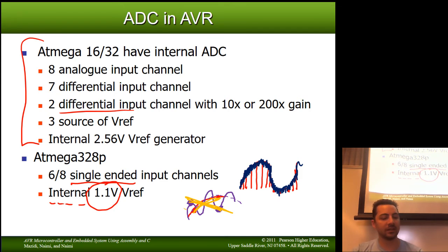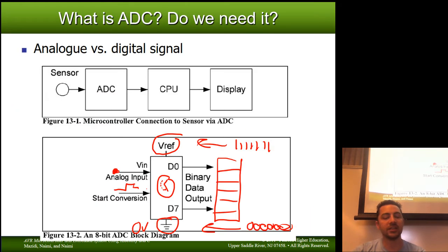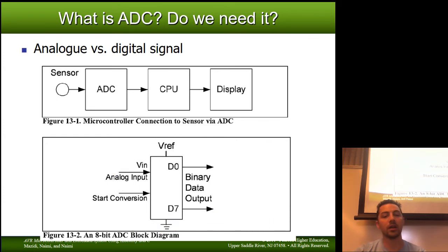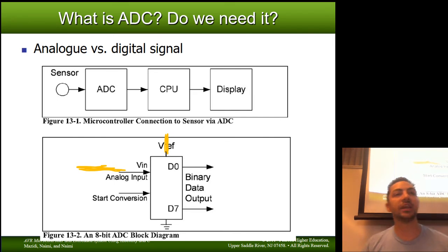So what that usually means is, if we have high frequency noise, it could be in one of two places. Go back to our first ADC here. Our high frequency noise could be on the analog input itself. But that's not the only place that high frequency noise can appear. It can also appear on your voltage reference. The easiest way I found to explain the phenomenon of noise being on your voltage reference is picture a slinky.